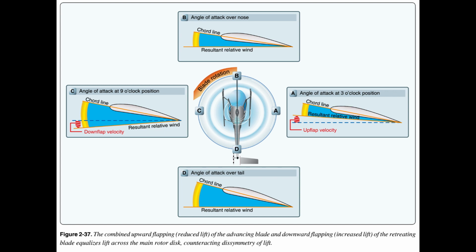of a helicopter. At a high forward speed, the retreating blade stalls because of a high AOA and slow relative wind speed. This situation is called retreating blade stall and is evidenced by a nose pitch-up, vibration, and a rolling tendency, usually to the left in helicopters with counterclockwise blade rotation. Pilots can avoid retreating blade stall by not exceeding the never exceed speed. This speed is designated VNE and is indicated on a placard and marked on the airspeed indicator by a red line.